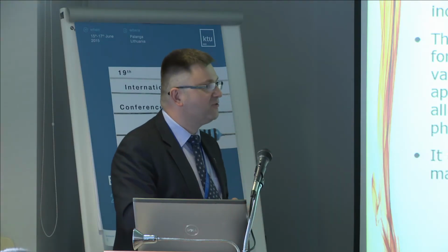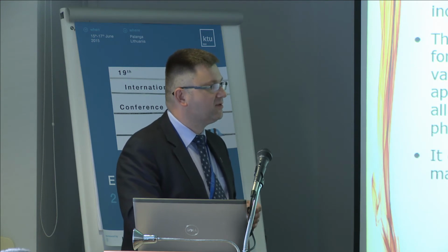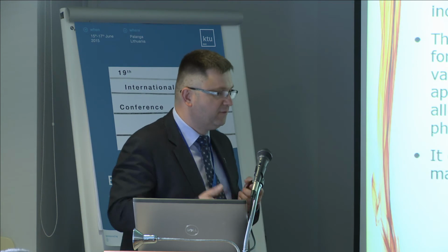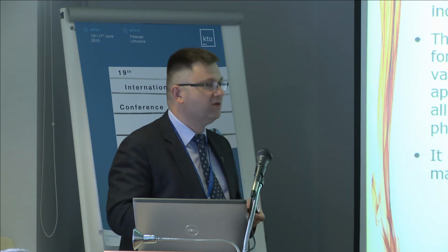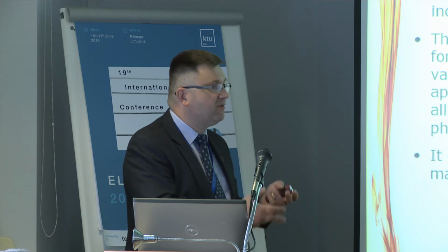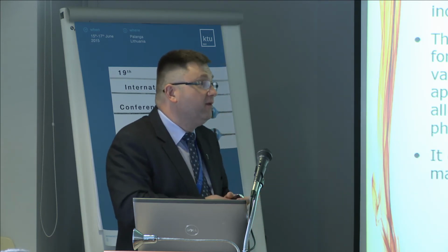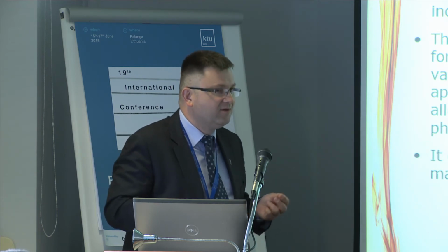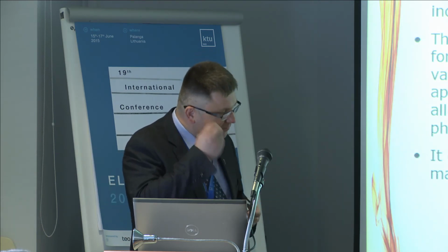But it's hard to correct such a sensor because the influence of temperature is much bigger than the strain. So you can use only smaller sensors or different kinds, but you have to watch.